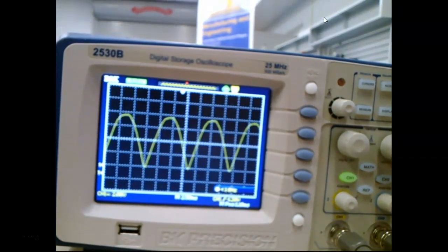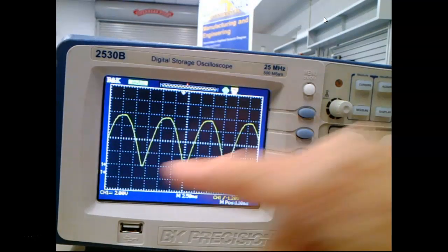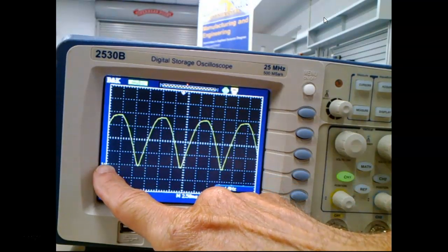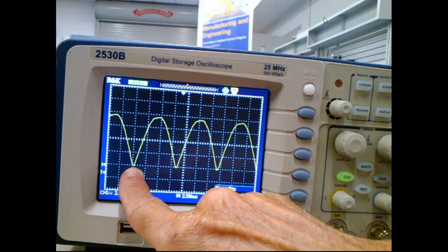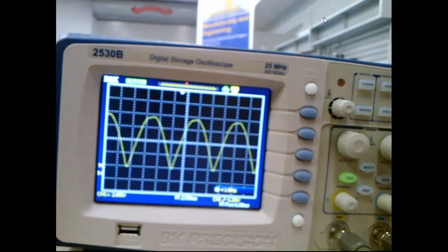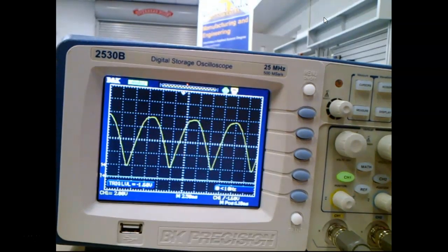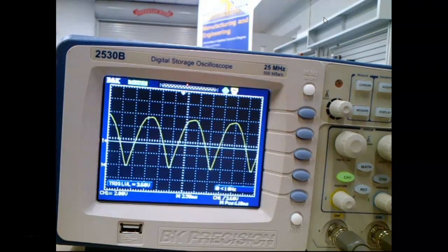And of course, we should notice a big difference. Now we have full wave, right? Here's my zero. I shifted my zero down here. So this is 0 volts. Looks like we might not be triggered. Can y'all see it moving? Just get that line within the waveform. And now it's away.